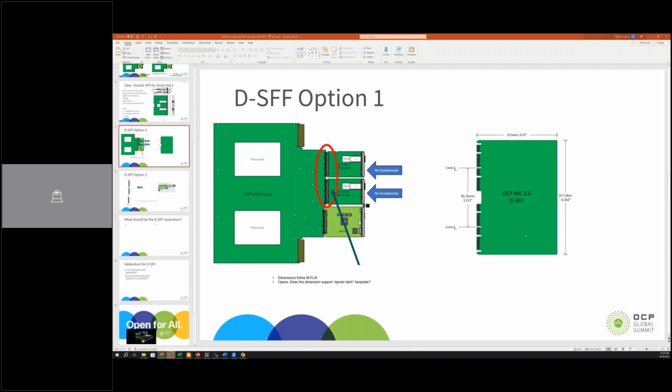For 800 gig, we're still investigating whether we can converge into an SFF, TSFF, whatever, but an SFF volume. We can converge electrically, layout-wise, but the question is whether we can converge thermally within a reasonable boundary condition, right? We have the real estate, we can fit it in the card. We have a relatively compact design, but the problem is cooling an 800 gigabit module,